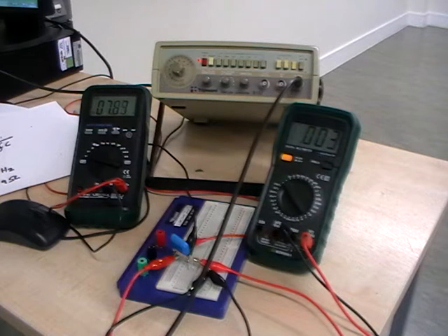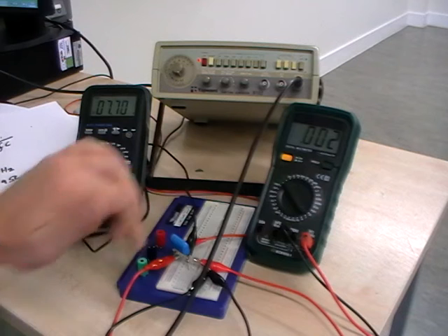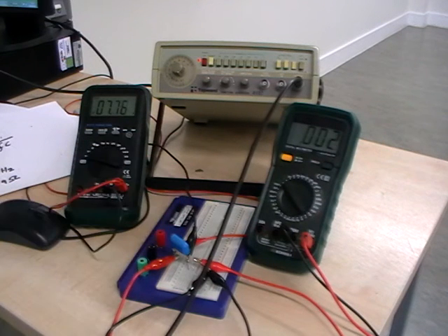Always remember, when you use Ohm's law, big resistances in a circuit drop big voltages, small resistances in a circuit drop small voltages. And so this resistor at the moment drops a very small voltage, and we know the resistance is 150 ohms. That means the reactance of this capacitor must be several thousand times higher. So it's got a very, very high resistance. So we are at the moment somewhere in the kilo ohm range.